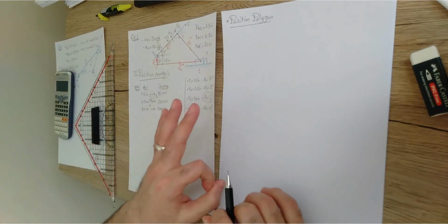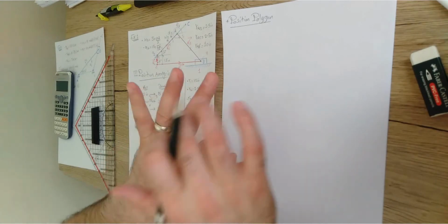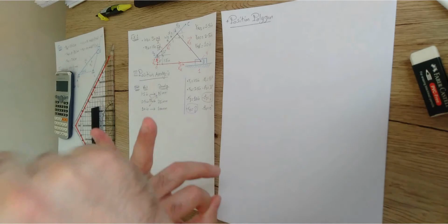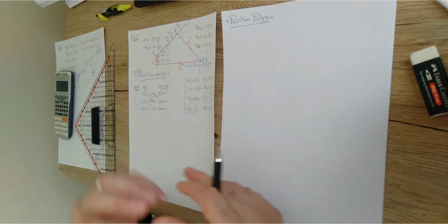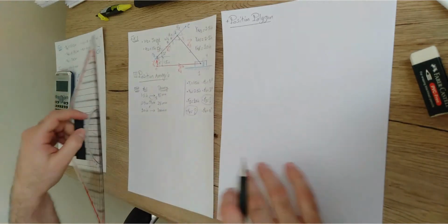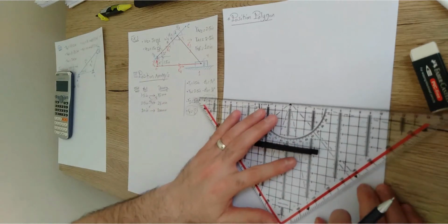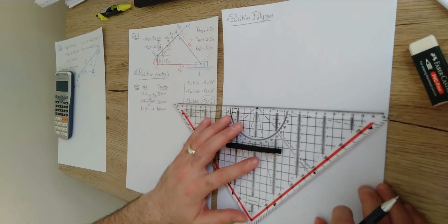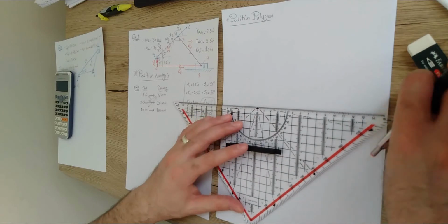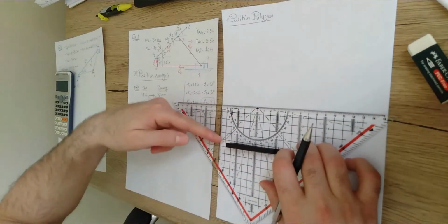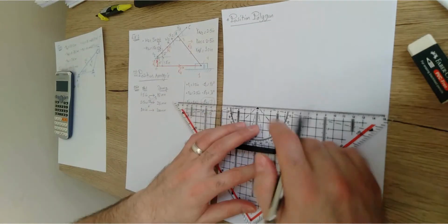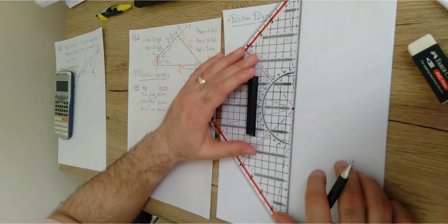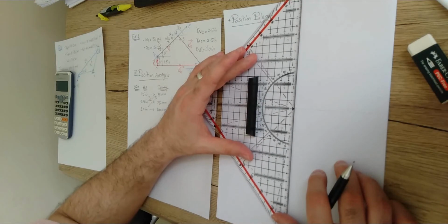As we agreed, the position vector should be drawn over 3 steps. The first step, just measure the angle. The second step, draw a light line over this angle. Then over this line, you're going to measure the distance, which is 1.5 or 15 millimeter. And this is what I'm going to do. But it is advised to have a general reference, that is a line that is horizontal in the drawing sheet. In this case, just try to align one of the edges of the sheet with one of these lines, and draw a very light horizontal line. This is a reference horizontal line, and we're going to have another reference line that should be perpendicular in this case.